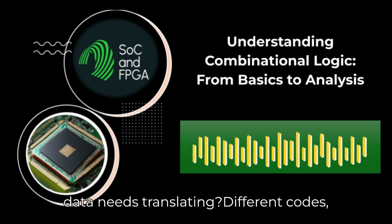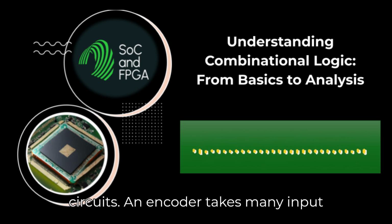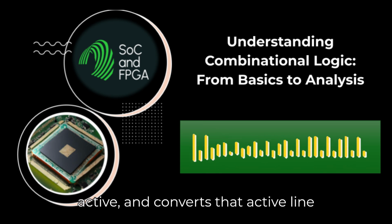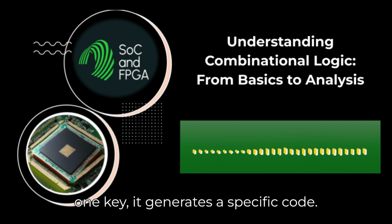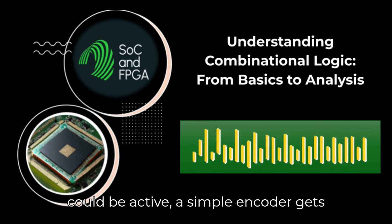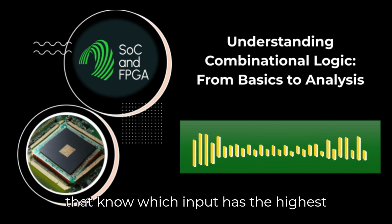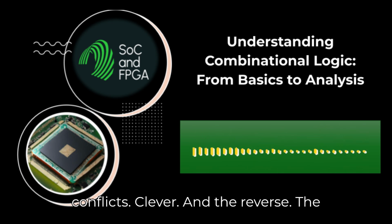What about when data needs translating? Different codes, maybe. That's the job of code conversion circuits. An encoder takes many input lines, usually assuming only one is active, and converts that active line into a compact binary code on fewer output lines. Like on a keyboard. Press one key, it generates a specific code. Perfect example. Now, if multiple inputs could be active, a simple encoder gets confused. So you have priority encoders that know which input has the highest priority if several are active at once, and only encode that one. Handles conflicts.